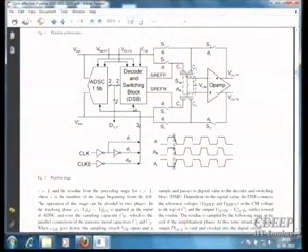Decoder and switching block, they call it DSP. So they have reference P and reference N. This reference P and reference N will be decided according to the logic bits which are generated here. And therefore what is connected this side to the bottom plate will depend on the bit which is previously generated.